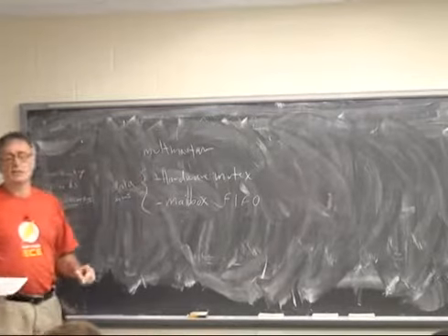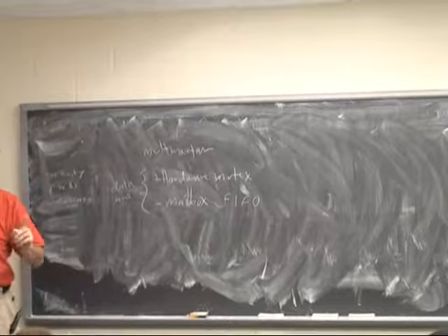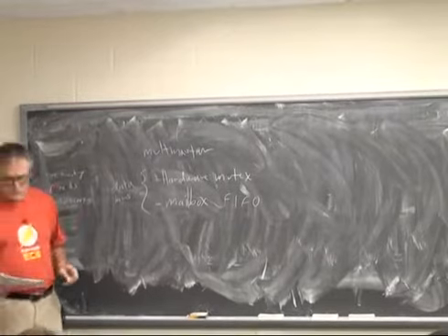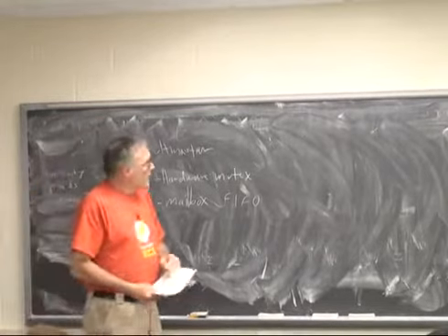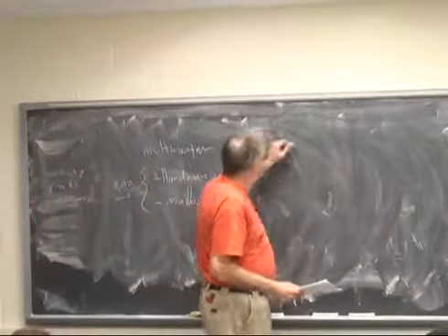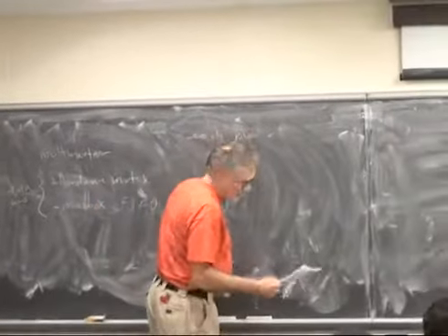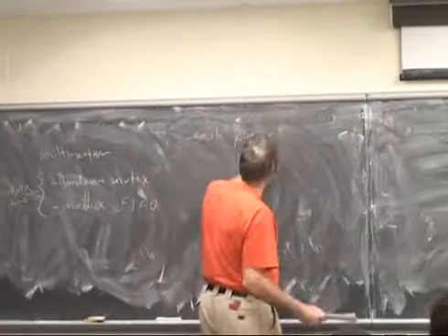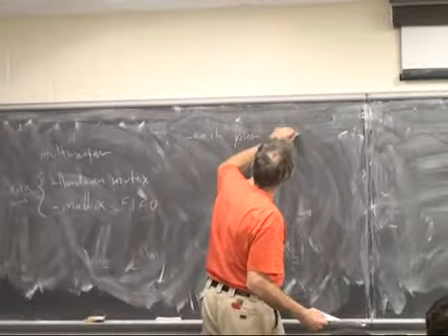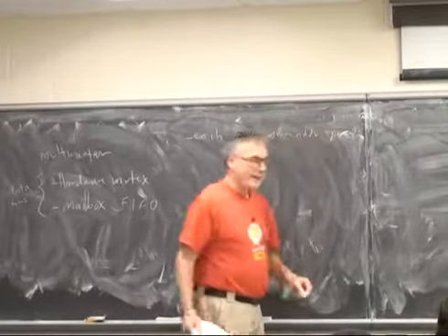Both of these get attached to the data bus on the Nios 2, on all of the Nios 2s. There are some limitations, or rules anyway. Each processor has to have its own address space. That kind of makes sense.